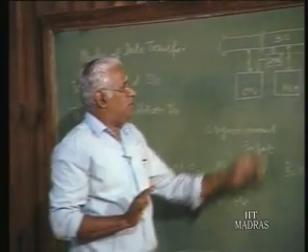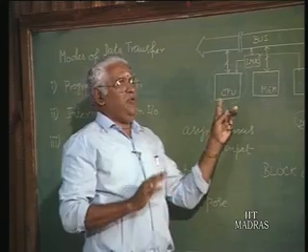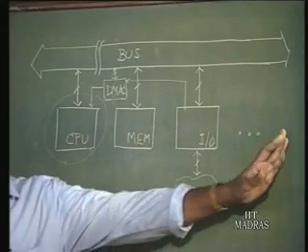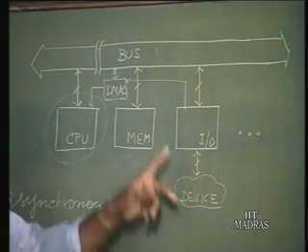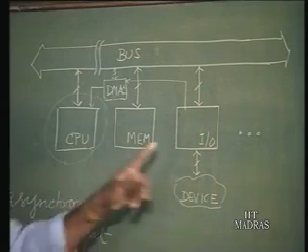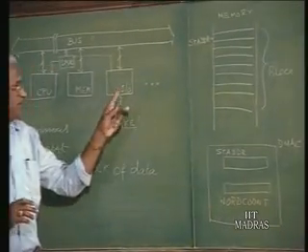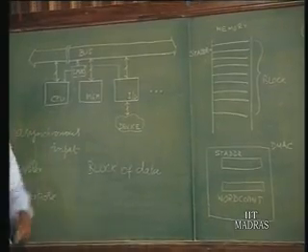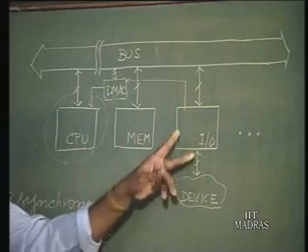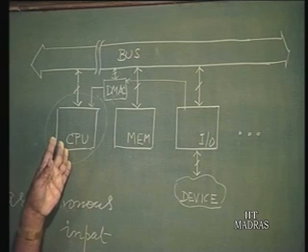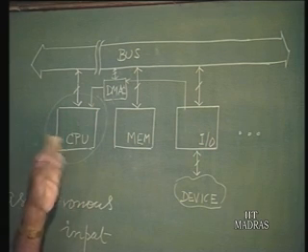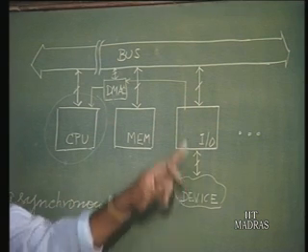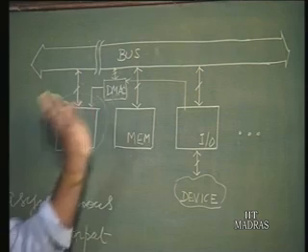Now, it is like this. Before the CPU proceeds with the program, it has got to configure all the IOs appropriately. Specifically in the case of DMA, it must have loaded these 2 pieces of information in the DMA controller, and then it proceeds with its own program. And when a device which requests a DMA transfer is ready, it is going to indicate. Now, how does it do it?